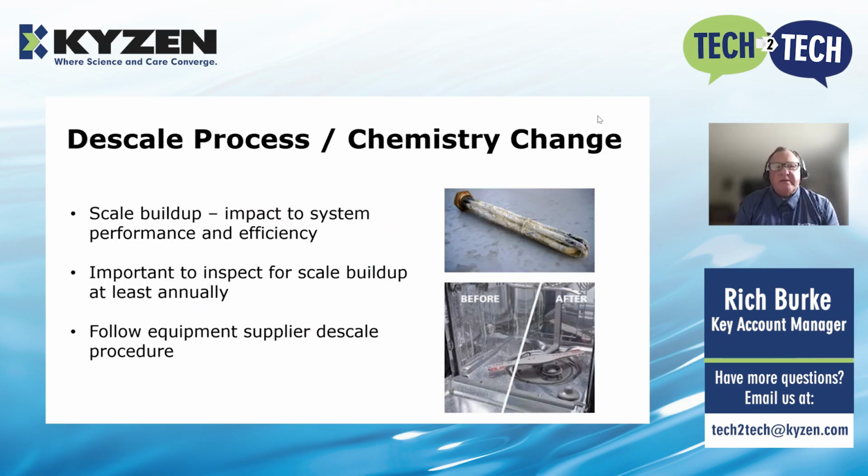So let's talk for a minute about the descaling process and chemistry change. Scale can build up within our system, on our immersion heaters, and on our nozzles and manifolds. As that scale builds up, it can affect the cleaning performance of our wash and rinse manifolds and nozzles, and in the case of an immersion heater, the efficiency of that heating system.